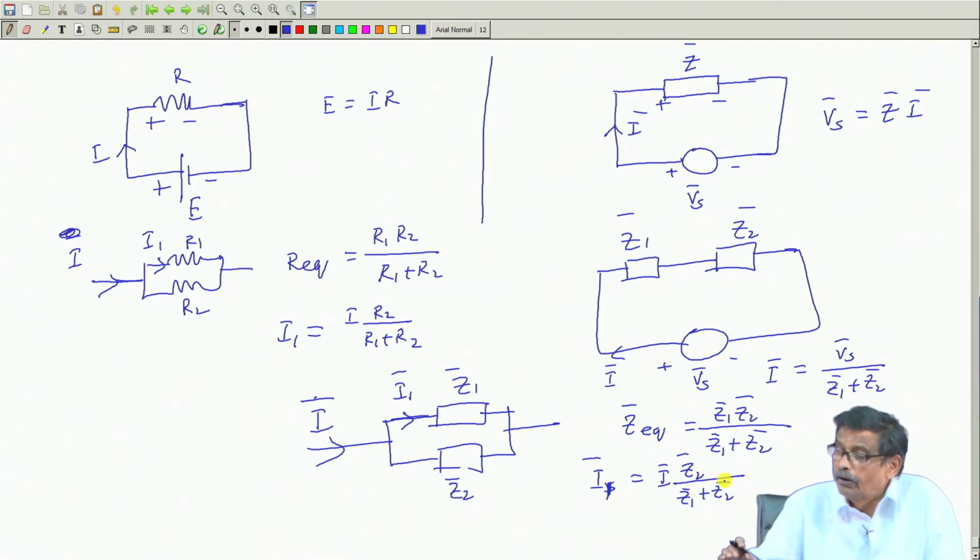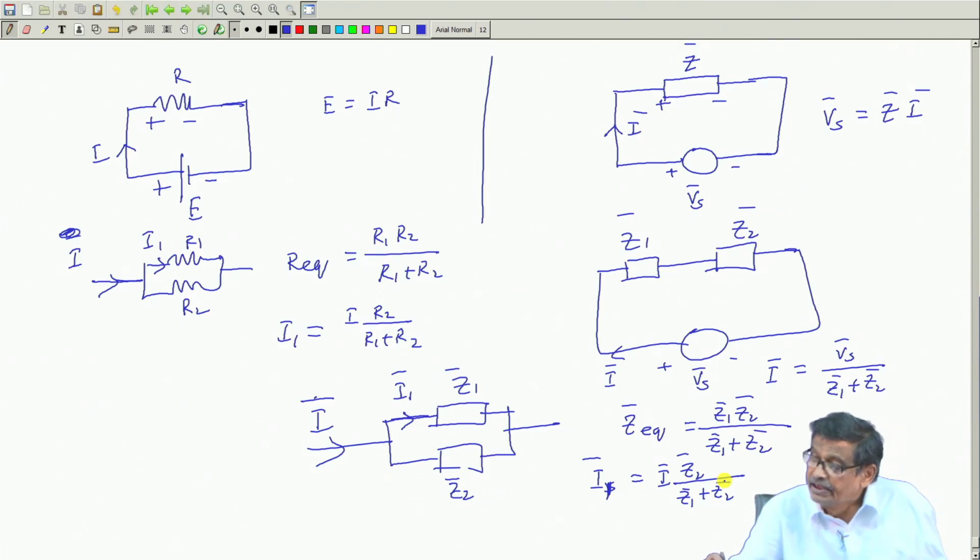See, the power of the phasor notation lies here, that immediately you get Vs equal to Z into I. Here is there any time term? No, only complex numbers. Once you get that, then all the rules of impedance manipulation, resistance manipulations, current divisions,